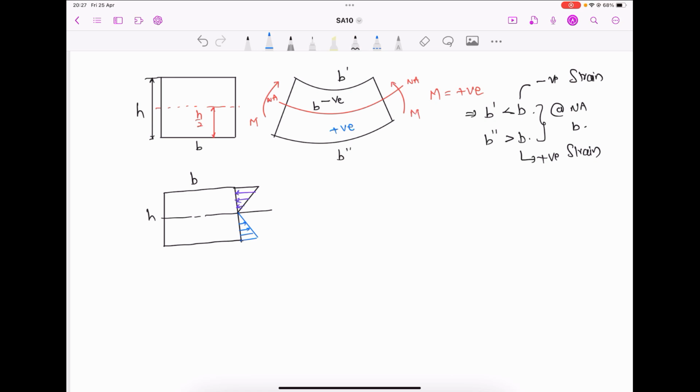the forces will pull. Here forces on top, force is compressive. Here force is pulling. It is pushing force. Please try to understand this clearly. Pushing force. Pulling force is tensile. There is a compression on the top, there is a tension in the bottom for the particular loading.